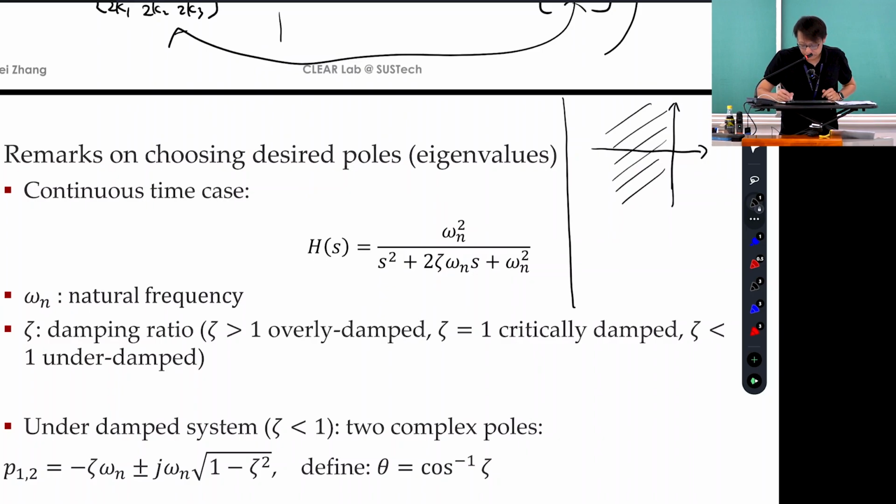Exactly the same question. If you ask me, those are engineering details, okay? Choosing what poles you want the system to operate at, there are some general guidelines, but there's no theory. To me, it's art, okay? But the key message I think everyone should know, if you forgot, you should recall it or learn it now, is that a rule of thumb is that you typically think about your system as a second order system.